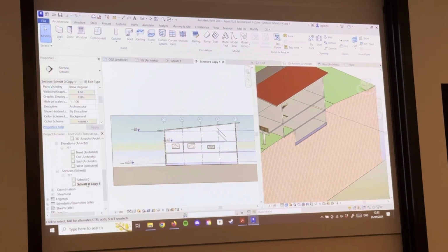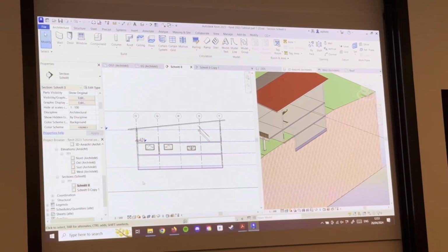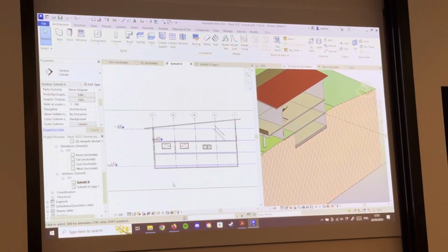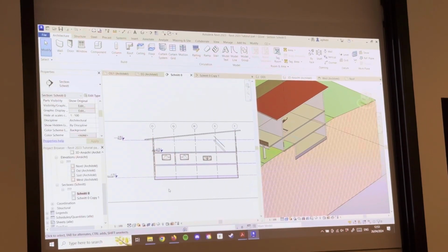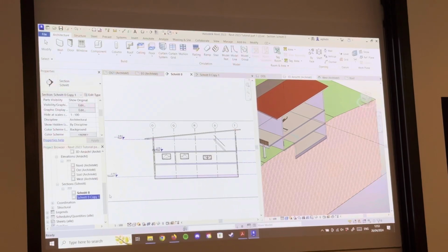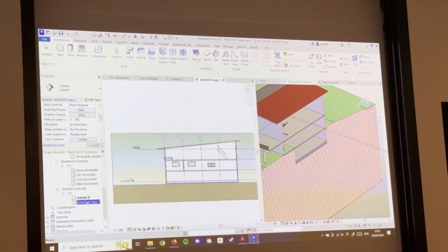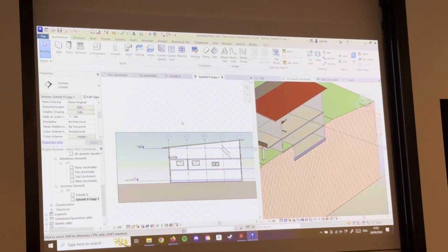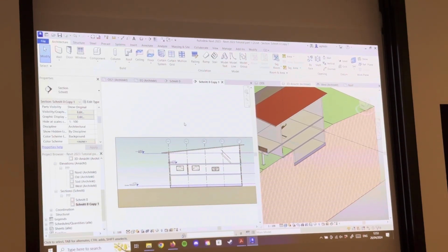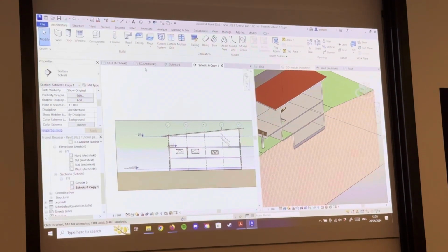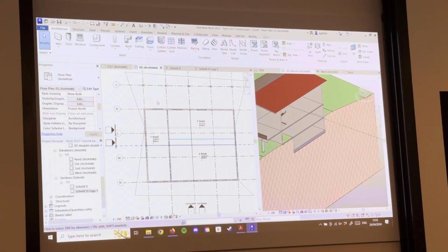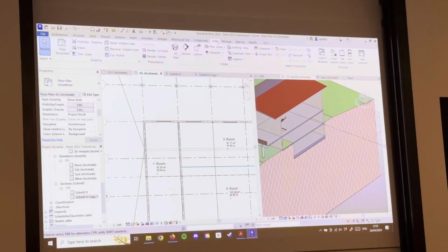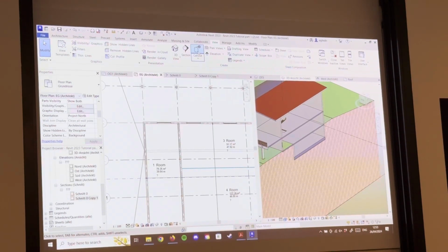So the thing is that now, if you go to the first section that we already had, it doesn't have these visuals that we added, but the new one that we duplicated has them. You might need it like this in some case. I hope you can manage to follow how to duplicate a view. I can move on to showing another way of creating more detailed views. You can go here into view, and you see here the call out option.